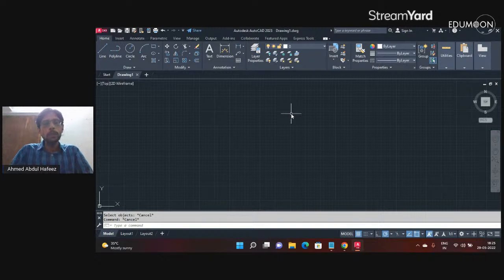That is different ways to use the enter key in AutoCAD. First is by using the enter key. Next is by using spacebar. User can make use of spacebar also in order to press enter. The third is, only in command mode, once you go for right click, the first option will be enter. So you can directly right click and pick the enter option. So you have three different methods to use enter key in AutoCAD: first is enter key, second is spacebar, and third is right click.